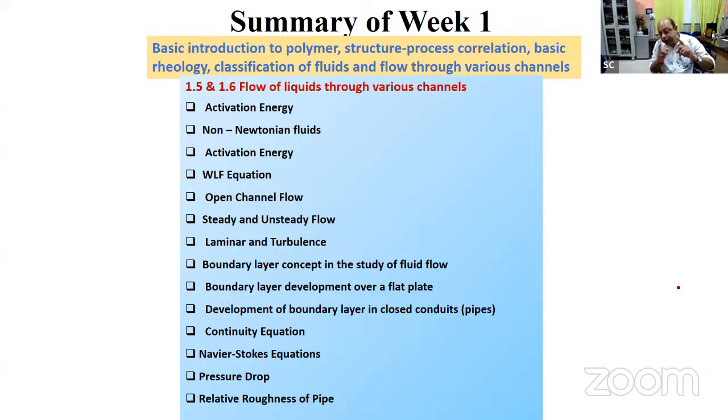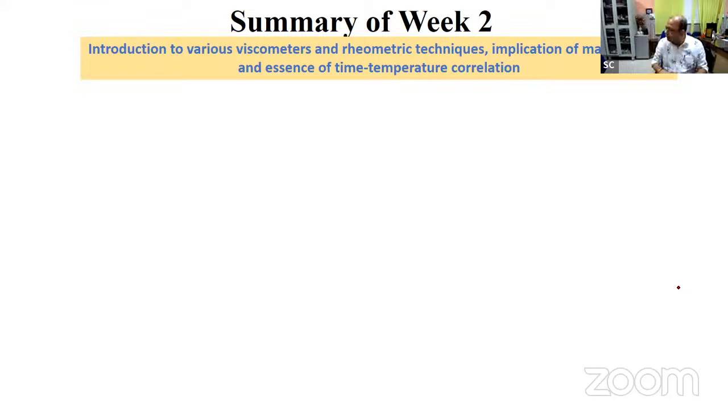So not only computing viscosity as a function of shear rate, but also the normal force differences as a function of shear rate is very important while predicting the shape of the material, and while predicting the roughness of the surface that you make by a unit process. So these are some of the implications in the long term that we will call upon again as and when required.